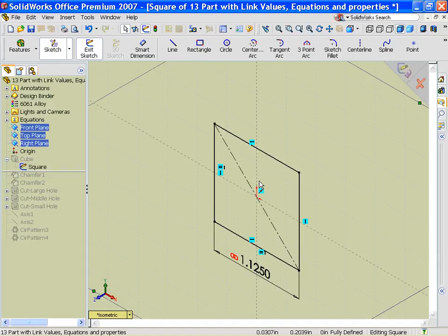So by having that origin in the middle, moving my planes to the middle of my cube, I now have a total of 9 different places to open a sketch, whereas on a standard cube, sketched out the way I previously mentioned with the lower right hand corner at origin, I'd only have 6 places to add a sketch, as like I said, 3 of those places would occupy the same spot as the other 3 planes.